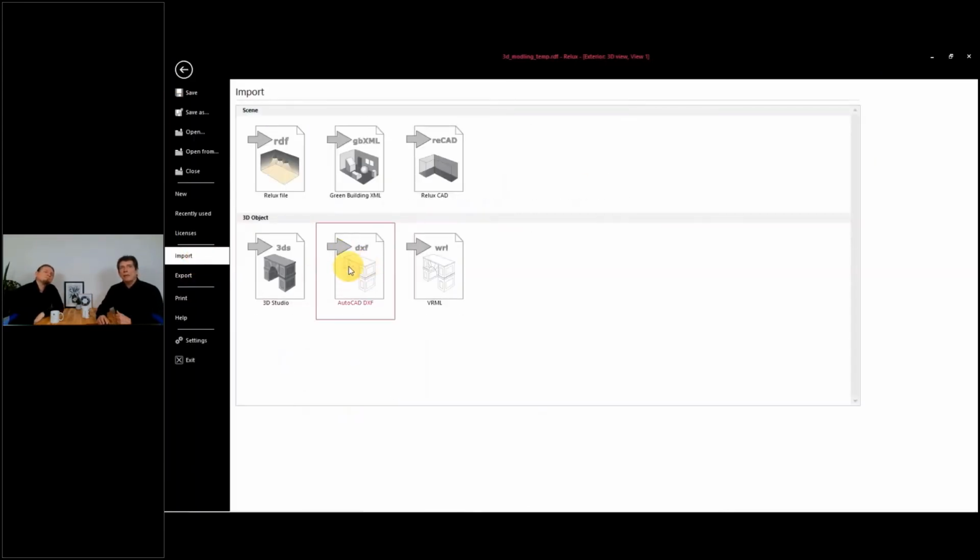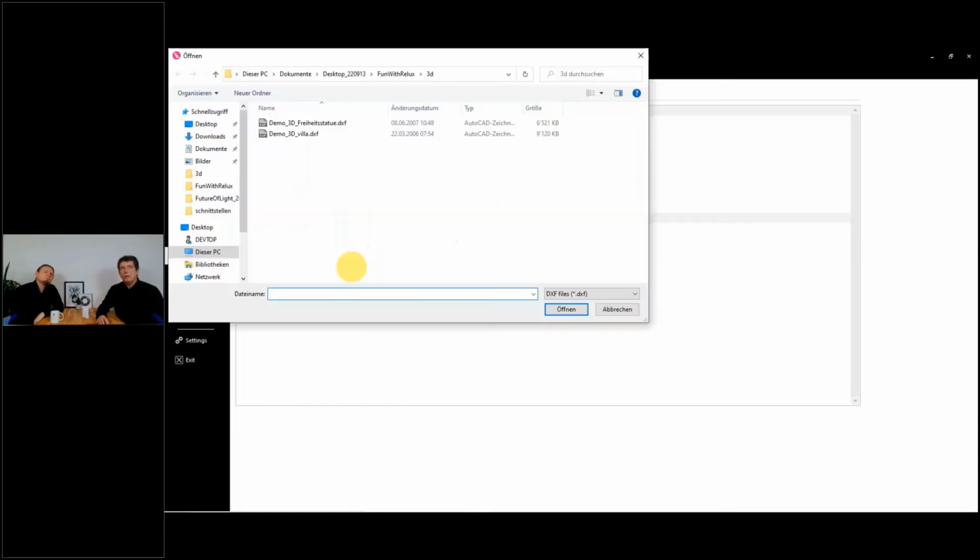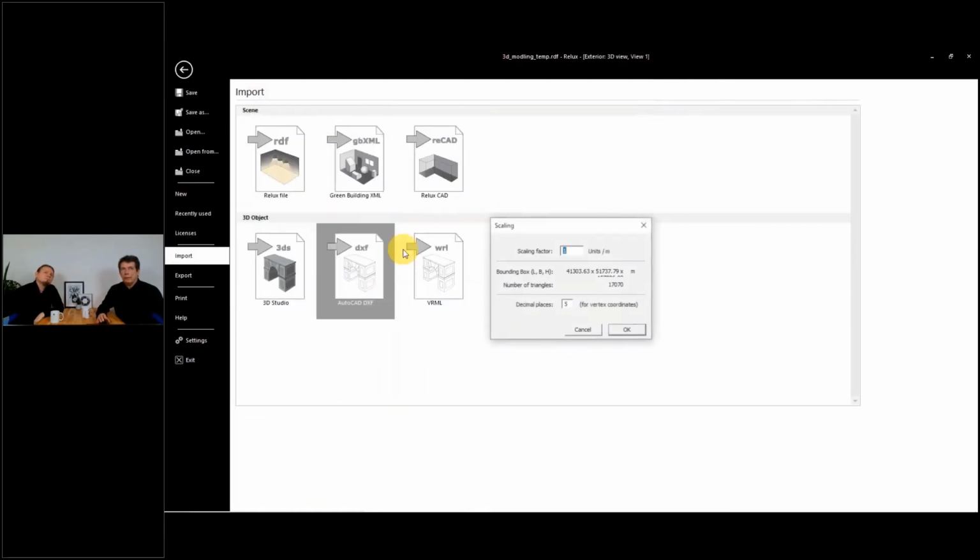As for the DXF, we must say it works only with DXF files which are face-based or mesh-based. In an AutoCAD DXF file, it can also be including solids and or just 2D lines. So sometimes people try to import here a simple 2D drawing, which we can import in the context of a background, as of a CAD drawing. There is the 2D information, the lines, layers, and these things are impossible here.